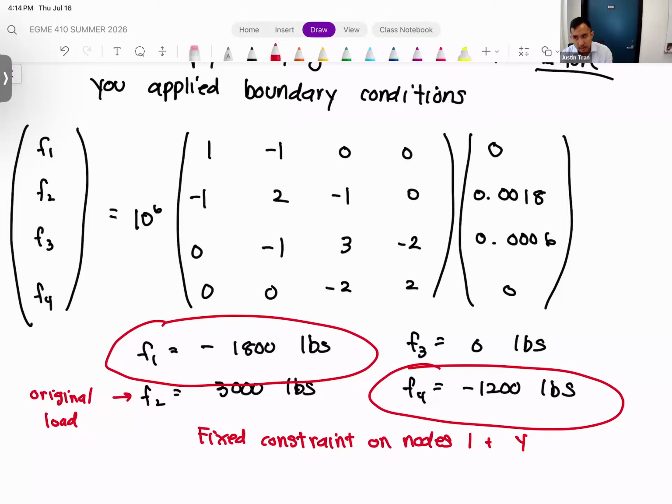If you load up the part inside ANSYS Mechanical or even in any of the CAD softwares like SpaceClaim or Design Modeler, there's a little ruler at the bottom in the middle. You can use that to get some rough measurements of how long the piston rod is and how wide it is. Then you can use that to estimate what kinds of forces are applied on a piston rod of this length. I think that'll help you narrow down your search.